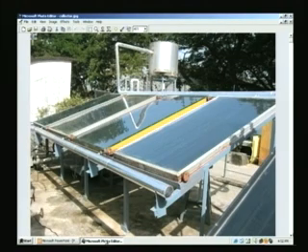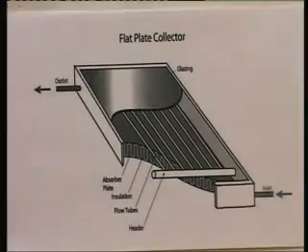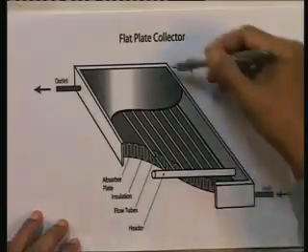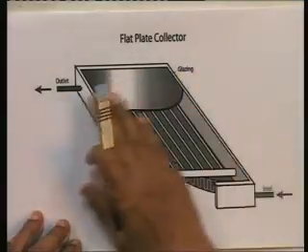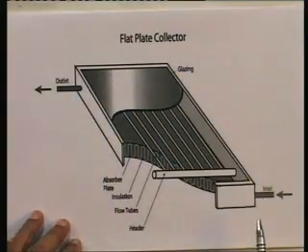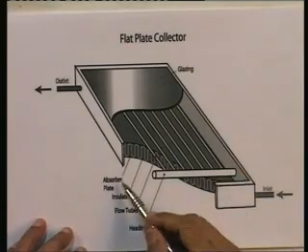Now, let us look at one such solar collector. There are 4 in the picture. I am going to now look at one. This is one collector, so that we see the inside of it, what it looks like. A solar collector, this is 2 meters in length, 1 meter in width as I mentioned. Typically on top there is a glass cover which you had seen in the picture, and below that there is an absorber plate. This is the absorber plate.